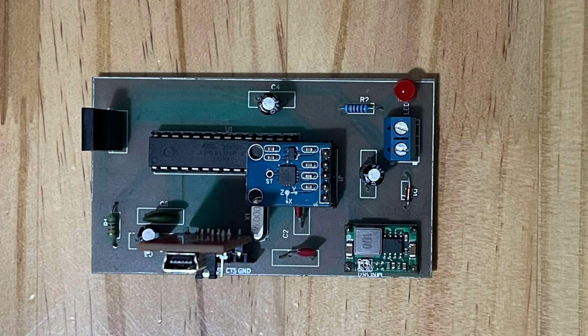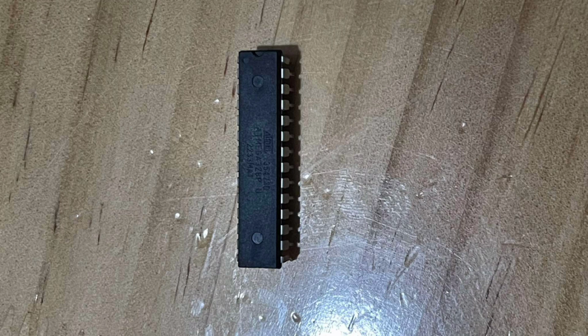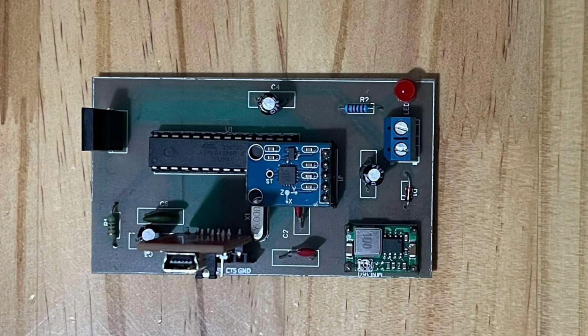Hello everybody, today I'm going to be explaining our predictive maintenance project focusing on both the circuit diagram and the PCB we built. As we can see here, at the center of our design we have the ATmega328P microcontroller. It is the whole brain of our system. It's going to be reading data, processing it, and controlling the output. To keep it running accurately, we added a 16 MHz crystal oscillator with two small capacitors for stability.